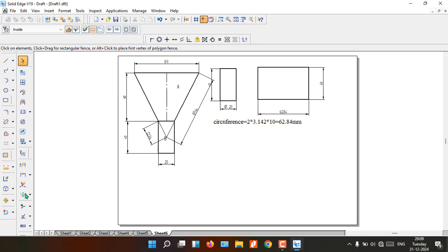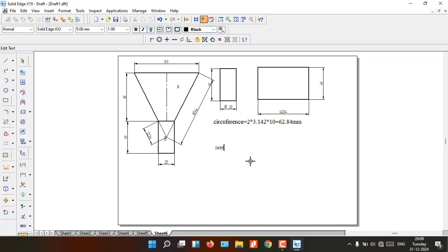So in order to develop a cone, we need the sweep angle. So we can say here the sweep angle will be equal to the radius, that is 40, divided by this 89.44 star 360. Okay, so that much angle. So we'll just calculate that one, maybe putting into the calculation.